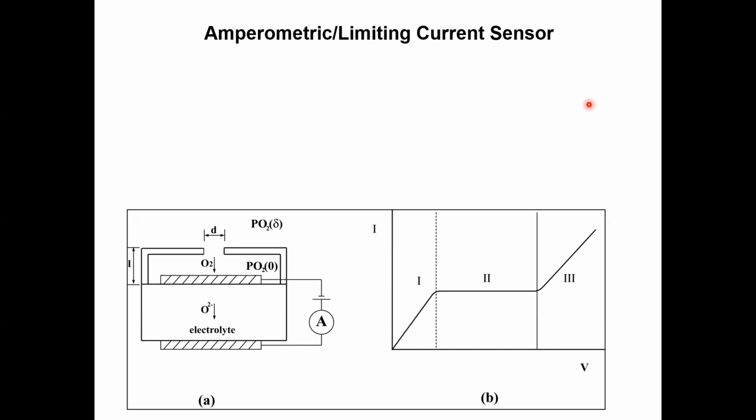So if you're trying to monitor, let's say, a continuous change in oxygen concentration, for example distinguishing between 21% oxygen in air versus an environment with, let's say, 15% oxygen, then if you take the ratio of 0.21 atmosphere versus 0.15 atmosphere, the signal is not going to be large.